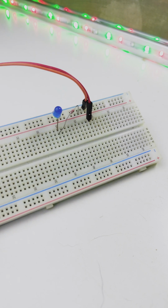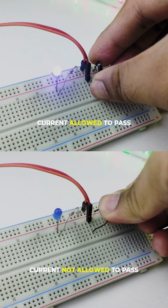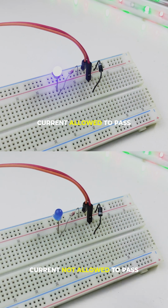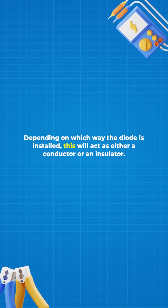As you can see here, if we connect the diode to a simple LED circuit like this one, we see that the LED will only turn on when the diode is installed the correct way. And that is because the diode allows current to flow in only one direction. Depending on which way the diode is installed, it will act as either a conductor or an insulator.